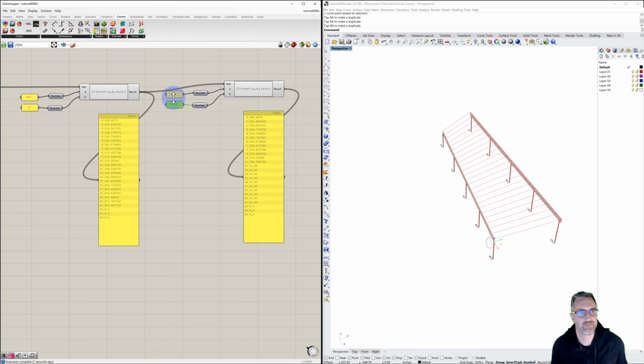Because remember, well, you don't have to remember, I'll tell you, that between 185 and 225 is an allowable depth for a 2x12. A 2x12 in dimensional lumber is 11.25 inches deep. So we can see what happened between these is that now our list that had anything between 185 and 225 has been translated into 11.25.